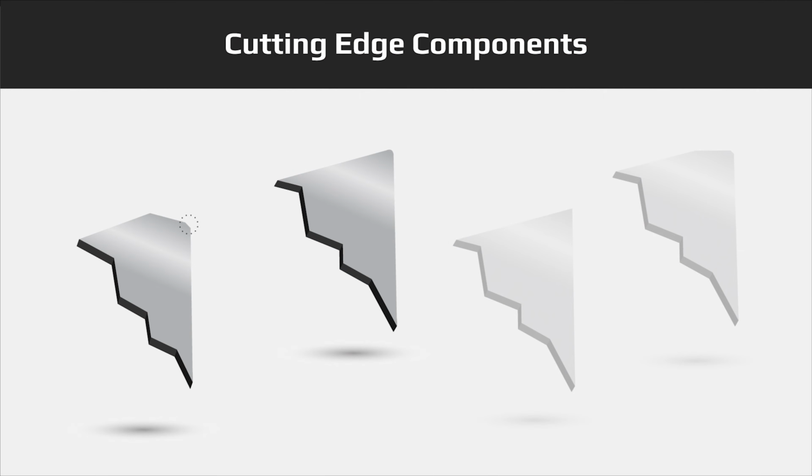The first area is the primary cutting edge, the first point of contact between the cutting tool and the material being machined. This area may have a land added for strength, as shown here, or it may not. The second area shows the side of the insert, what is sometimes referred to as the flank. Now, this is where the normal flank wear that dictates the remaining tool life should generally be measured. The next area is the rake, where the chip created while machining will flow across the insert face. Now, this area may have a chip breaker or it may be flat. Finally is the hone, which is basically a rounding of the cutting edge to provide a bit more strength.